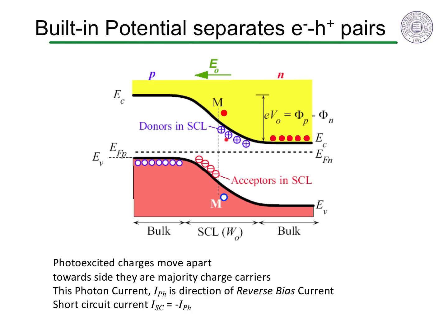When a photon makes an electron-hole pair in the depletion layer of a p-n junction, the charges created immediately feel the electric field from the built-in potential. The field makes the holes drift towards the p-type region and the electrons drift towards the n-type region. Note that these are non-equilibrium electrons and holes, so they are not driven by the equilibrium Fermi level that includes diffusion forces, until they thermalize.